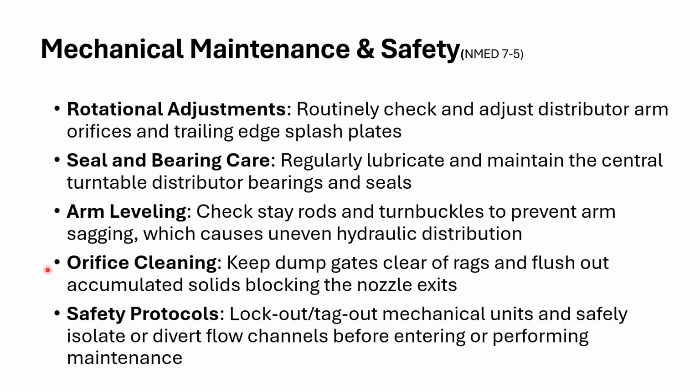If a rag or some rags get into the distributor arm, it's going to clog up the holes. You're not going to be able to flush. So rags, like I said, you want to treat and get rid of earlier on in the process, in the preliminary treatment process with the bar screens, with the comminutors, what have you, simply because this is one of the areas where they'll cause problems.